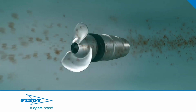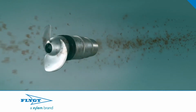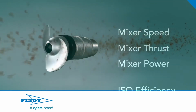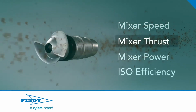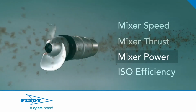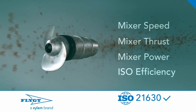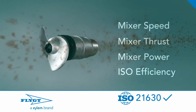To help determine the appropriate mixer, you should look at 3 key parameters: mixer speed, the thrust it is generating, and the power it is consuming to generate that thrust. This information tells you how hard the mixer is working, how efficiently it is delivering the needed thrust, and, of course, what it is costing in energy consumption. Remember to look to the international standard, ISO 21630, for unbiased thrust comparisons between mixers. Never settle for rules of thumb or unsubstantiated claims.